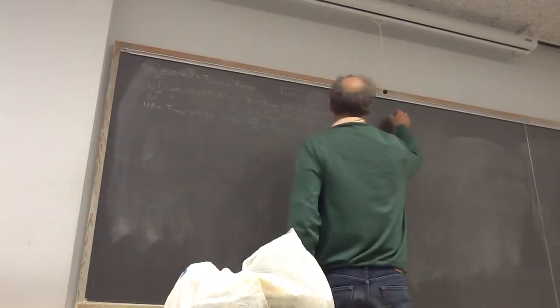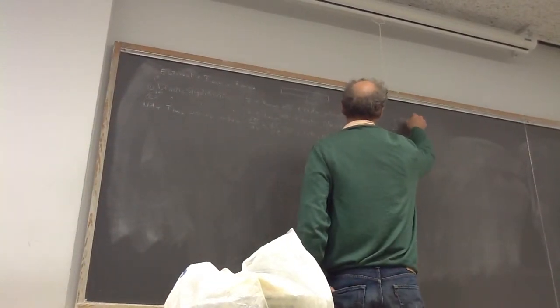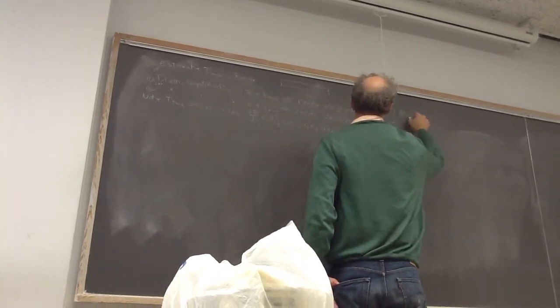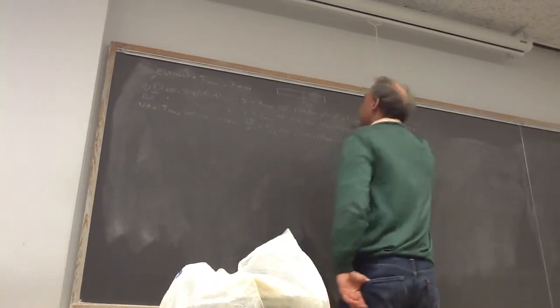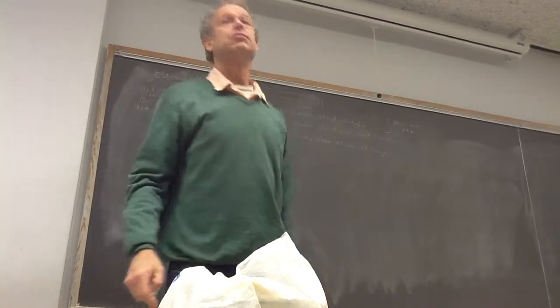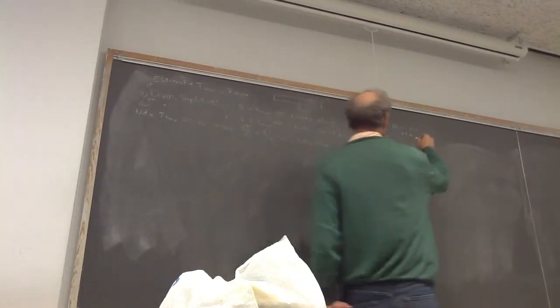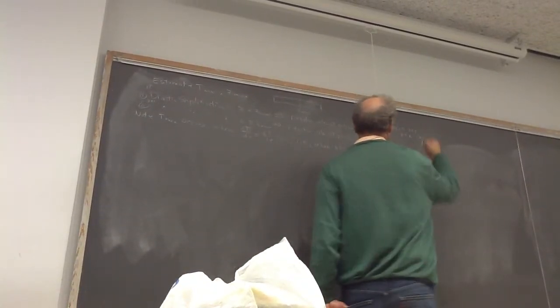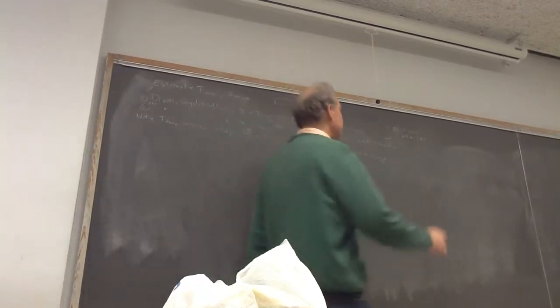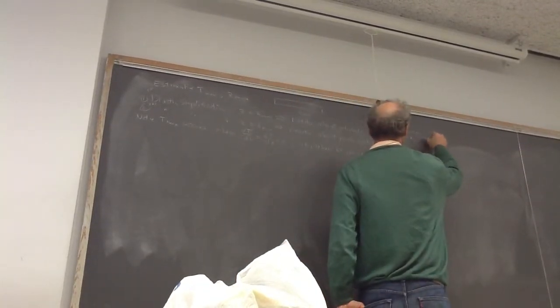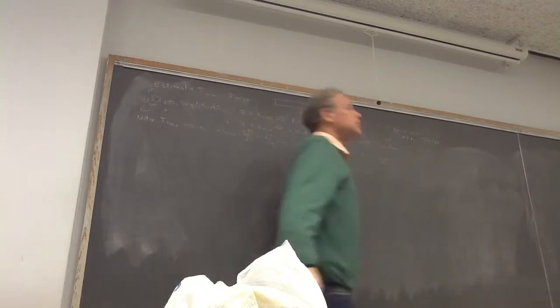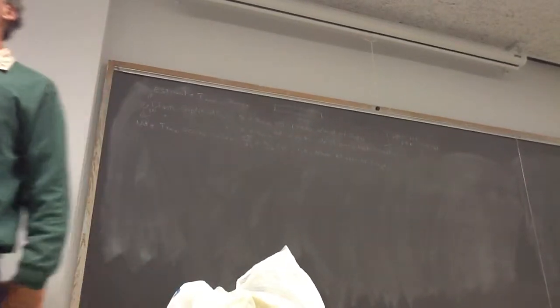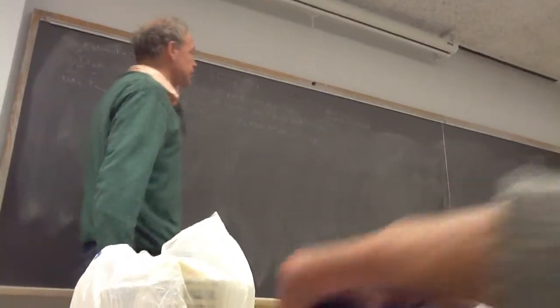So I'm going to plot heat generation from the adiabatic curve, meaning as a function of Z. From the heat generation, I'm going to get T of Z. From purely adiabatic, I'm going to get a T of Z for Z less than Zmax.